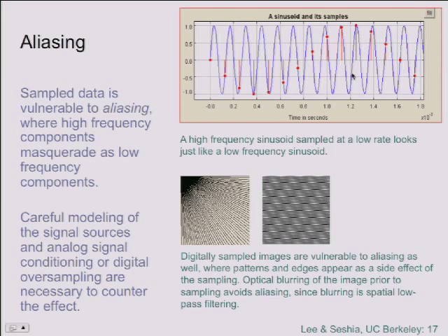Aliasing also arises in multidimensional sensors, such as image sensors. This is an image sensor where the finite precision of the pixels produces these so-called moire patterns. These patterns that you see of this sort of bug-shaped phenomenon here, those are artifacts of the sampling. Those are not properties of the original image. And similarly, these stripes that you see are artifacts of the image. This image is actually just horizontal stripes slightly tilted. Okay? There's no vertical stripes in this at all. It's just horizontal stripes slightly tilted and being sampled.